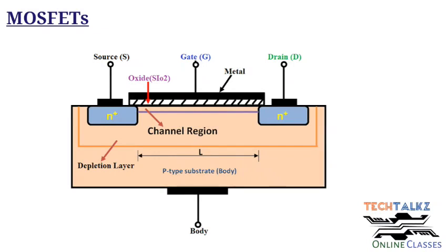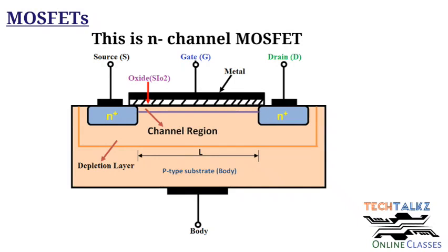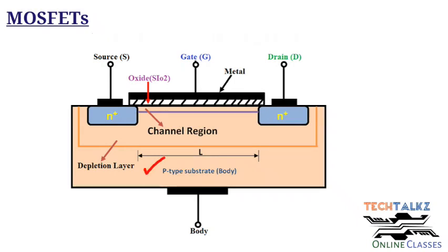So you may be familiar with the MOSFETs, that is metal oxide semiconductor FETs. So here is P-type silicon substrate, N-type source and drain, and this is the gate. The gate may be metal or polysilicon, conducting polysilicon. This region, that is metal, then thin oxide and P-type semiconductor, that is the substrate. So this is an equivalent MOS capacitor.